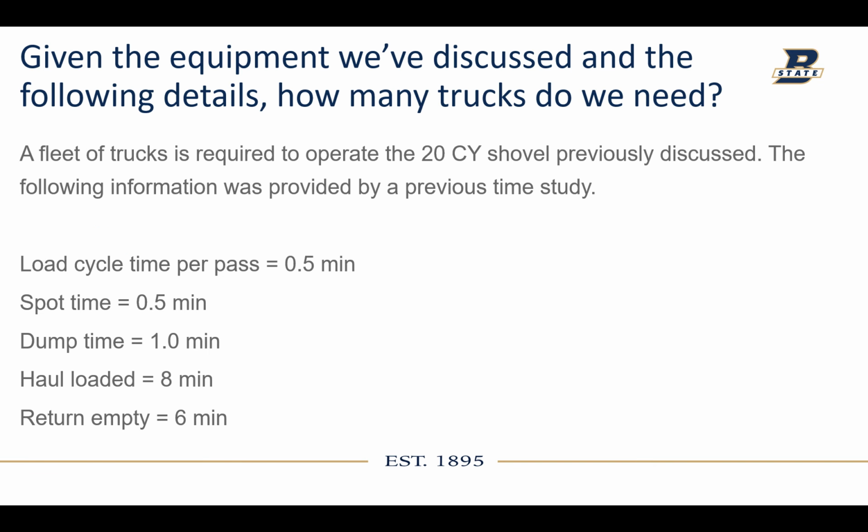So let's do some more practice problems. Given the equipment we've discussed and the following details, how many trucks do we need? So a fleet of trucks is required to operate the 20 cubic yard shovel previously discussed. And the following information was provided by a previously conducted time study. Okay? And so we have the load cycle time per pass, half a minute. Spot time, half a minute. Dump time, 1 minute. Loaded haul run, 8 minutes. And the return empty, 6 minutes.